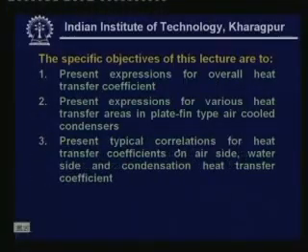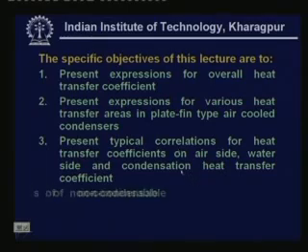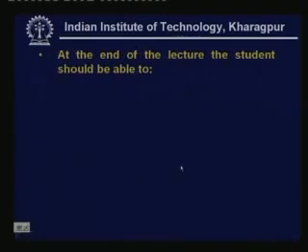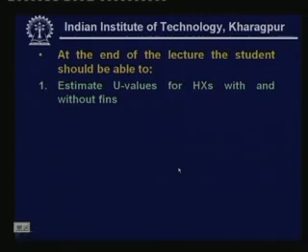Welcome back. The specific objectives of this particular lecture are to present expressions for overall heat transfer coefficient, present expressions for various heat transfer areas in plate fin type air cooled condensers, present typical correlations for heat transfer coefficients on air side, water side and condensation heat transfer coefficient, and discuss effects of non-condensable gases. At the end of the lecture, you should be able to estimate the overall heat transfer